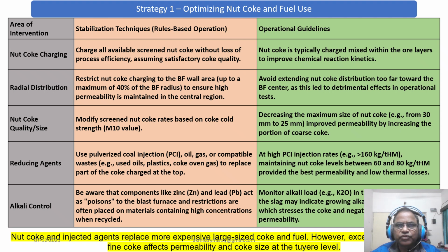A high rate of ferrous fines, defined as over 3% of ferrous burden, should only be used when blast furnace operation is good and stable. A stable operation requires a low heat flux as well to maximize the use of these fines.